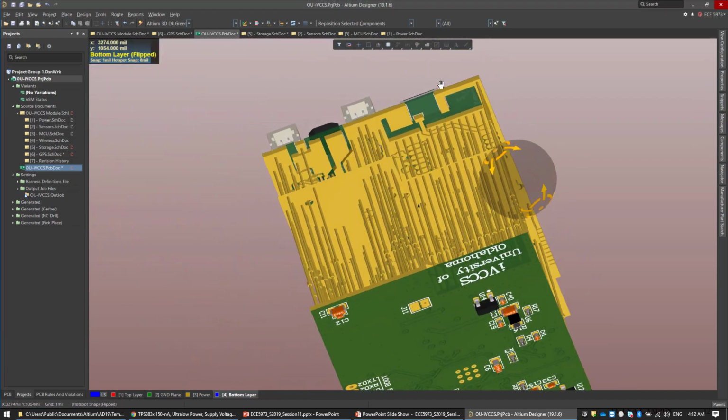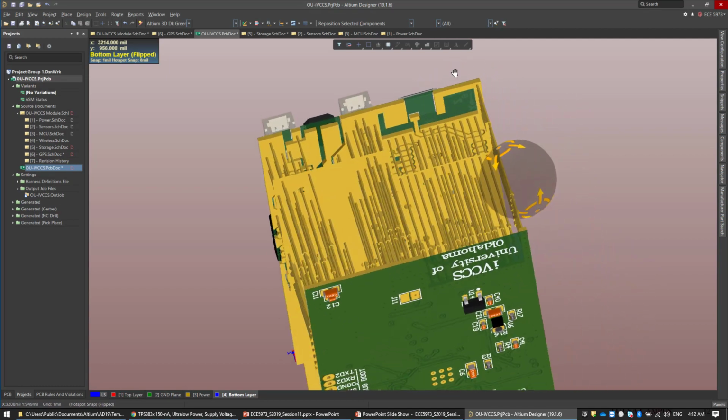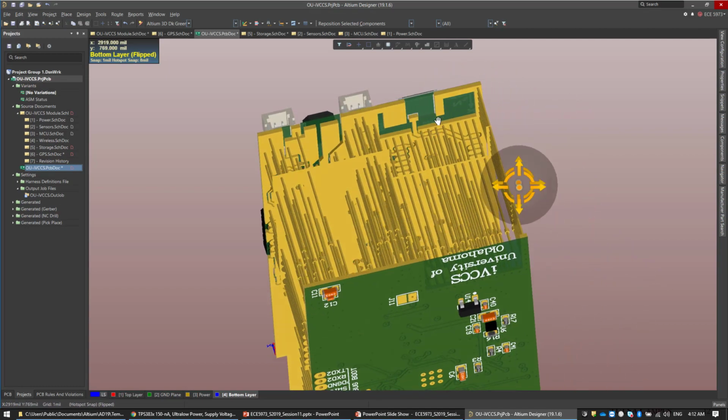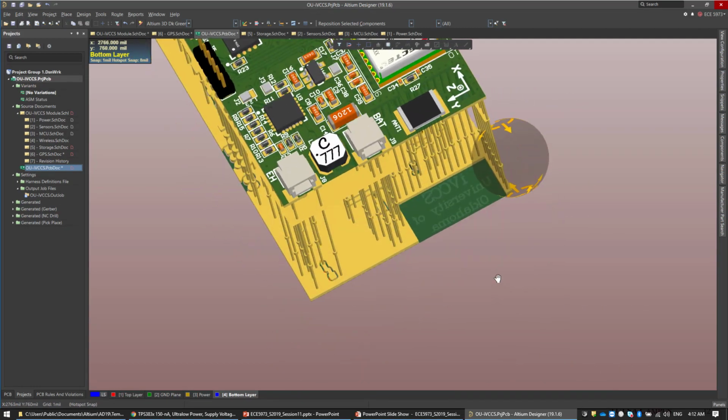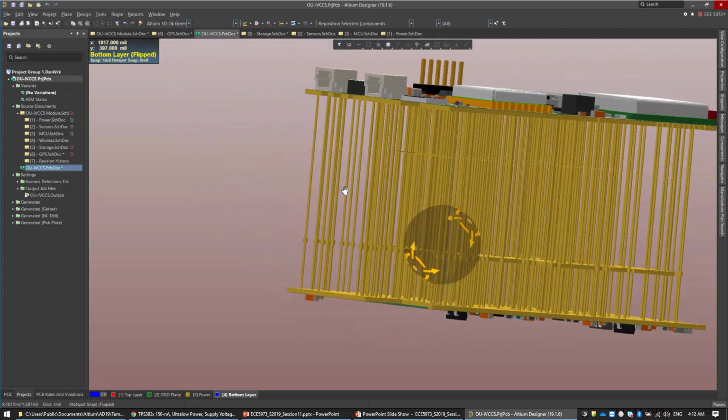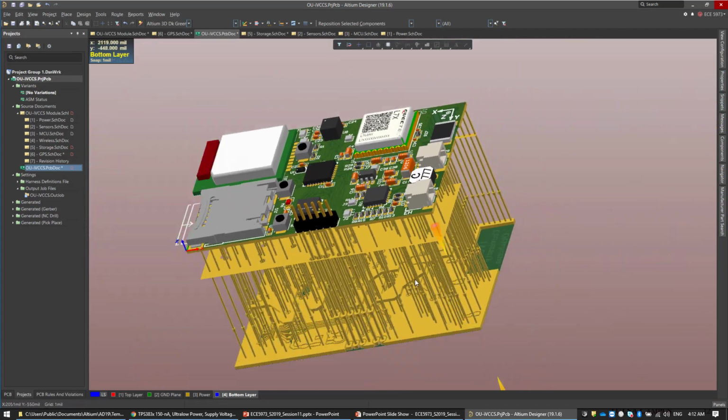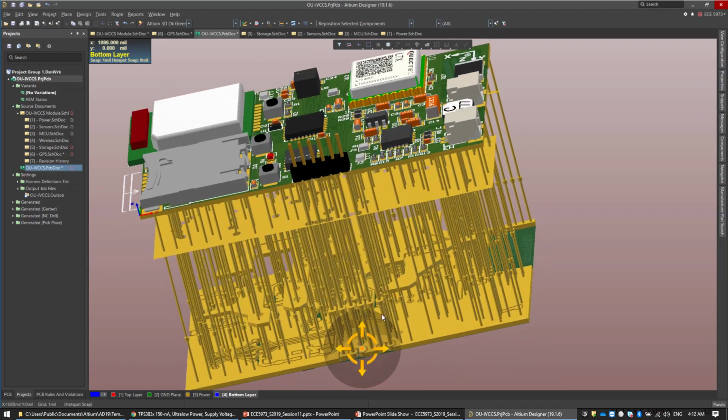So there is no cover over all the layers. It's keep out area and no cover at all. And it's empty. We need to make sure that nothing will attenuate the antenna signal. And here you can see the vias, how they are connecting into different layers.